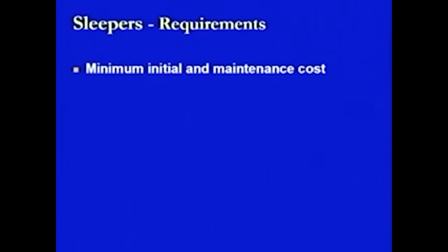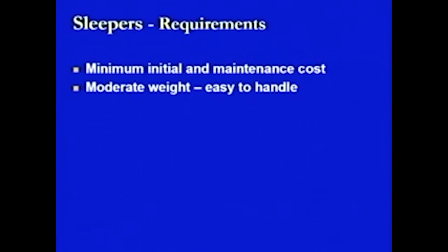So, based on all these functions which we have seen, now we are going to look at certain requirements. The very first requirement always remains with respect to the cost. The initial cost as well as the maintenance cost of the sleepers should be minimum. They should be of moderate weight, and they should be easy to handle. This is of course related to each other. If the weight is quite low, then obviously that is the easiest condition to handle the sleepers, but then in that case the stability or the stiffness of the track will not be there.